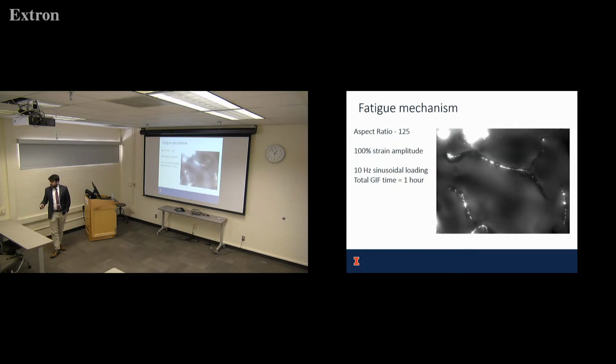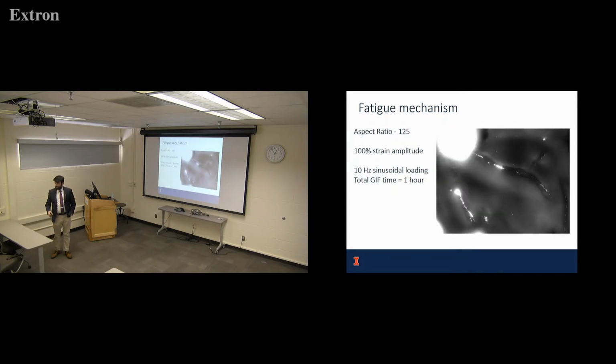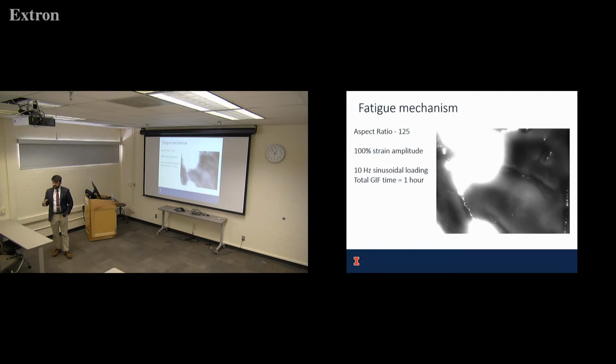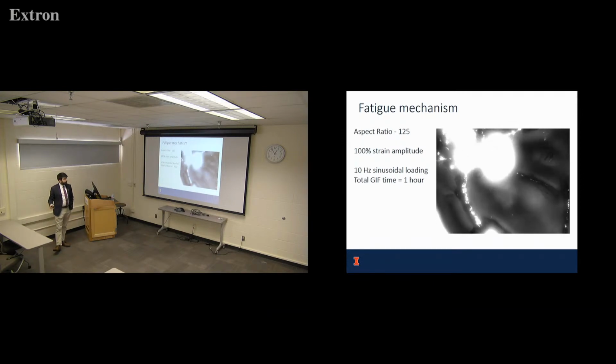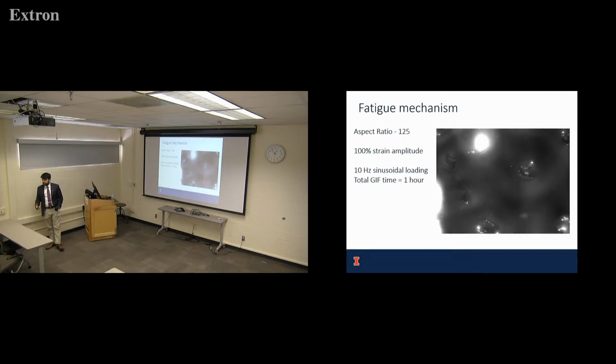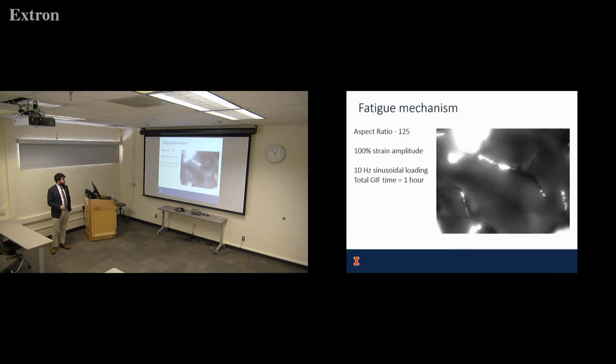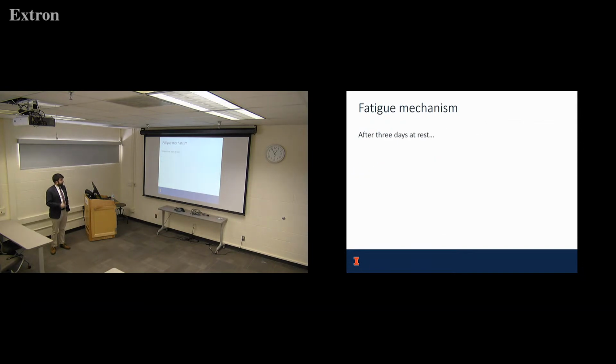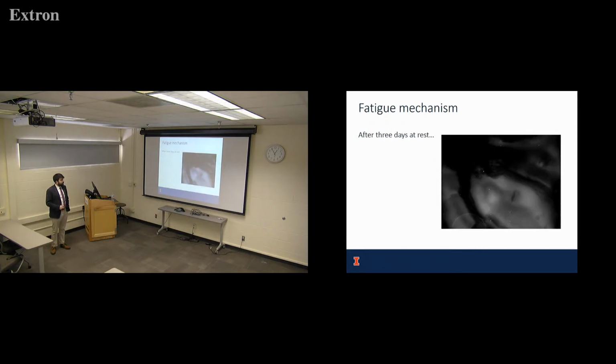And we wanted to say, what about healing? So where can you still heal? Where can you recover the damage in the material, and where can you not? With cavitation, we usually saw that the material could pretty much fully heal or leave just a very small cavity. But in this case, we left this one to rest for 3 days, and we saw those cracks didn't heal. So that appears to be more permanent damage. At least without heating or anything, you're going to see those as permanent damage.